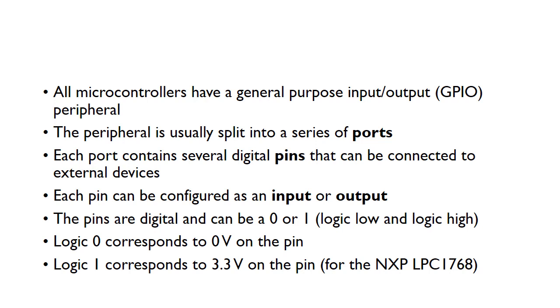As I've said, these pins are digital, which means they can either have a logic 0 or a logic 1 on that pin. The logic 0 corresponds to 0 volts on the pin, and a logic 1 will correspond to 3.3 volts on the pin for the case of the NXP LPC1768 microcontroller.